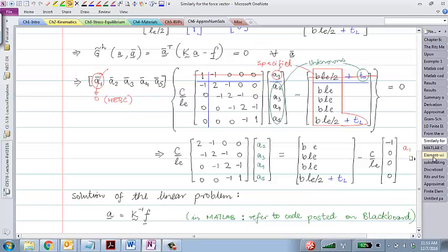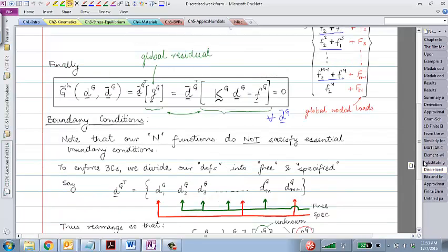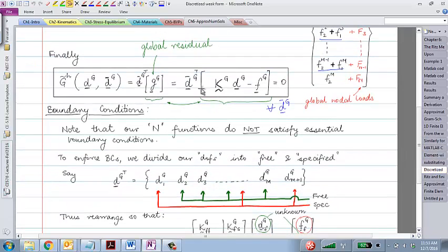In this approach, we do something very similar, and what we say is that for all of these degrees of freedom, these are the virtual coefficients and this d are the real coefficients. If I arrange them in a sequential manner, then some of those degrees of freedom in general are what we call free degrees of freedom, the ones that I want to find. These are the unknown coefficients for the displacement, and some of those degrees of freedom may be specified.